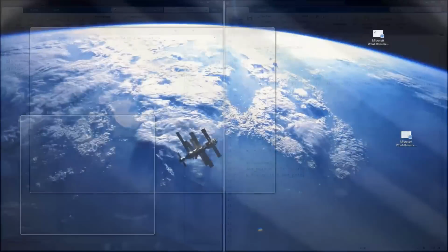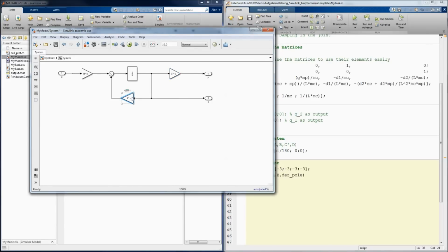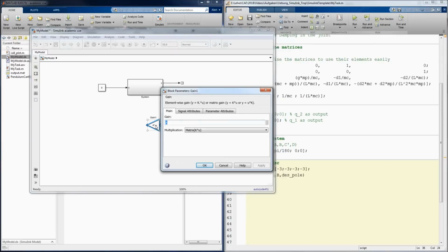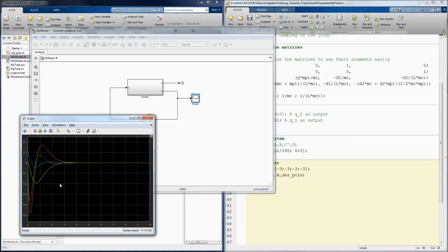And now you can basically feed back your state here to there. For that, you can even copy the gain you have been using here, call it k. Of course, it should be a negative feedback, that is -k. Let's remove this one here, and you see now once you run your controller, the system is stabilized.